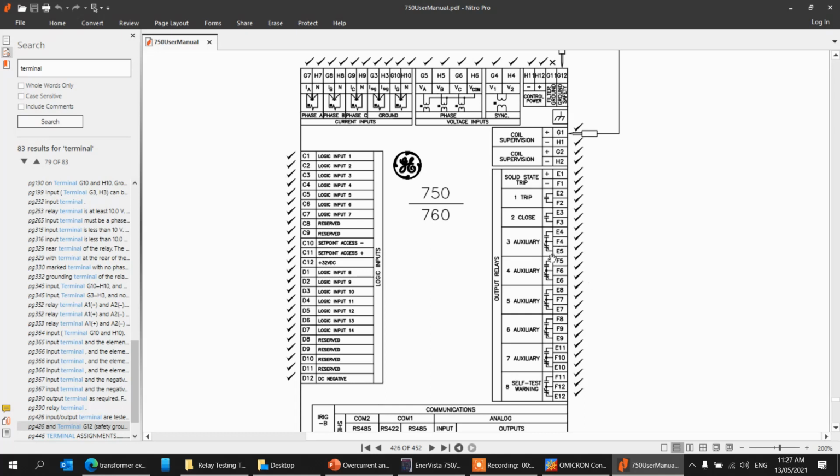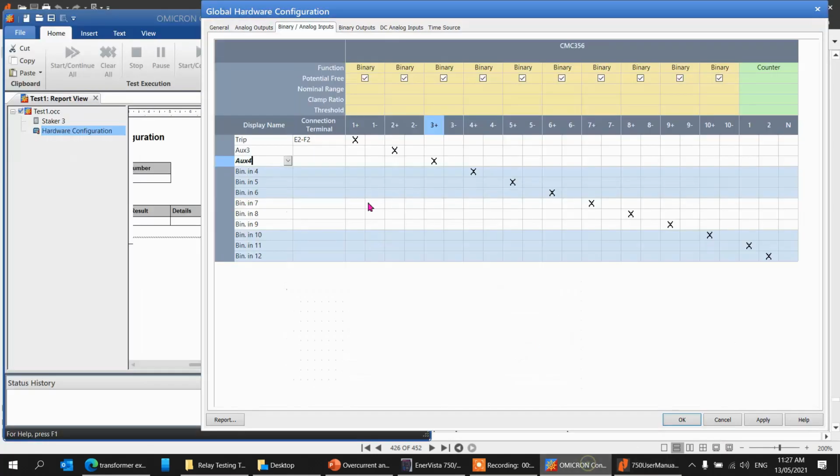Like for example, this one, you never pick up the normally closed. There's a common of F4. So if you're expecting a close contact, you put it in the normally open contact here of E4, F4. Correct, yeah. So E4, F4. So we can put that one there.